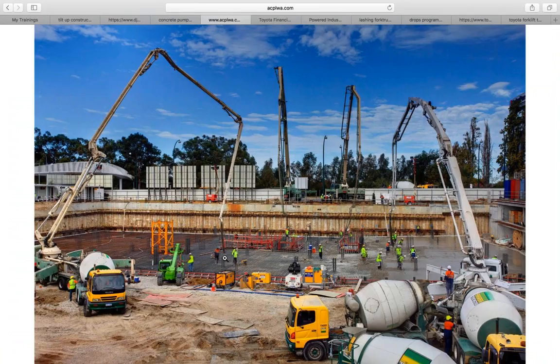Okay. All right, good. And then let's talk about chemical dermatitis and silicosis, right? Obviously, we want to control any type of dust in the air, silica, preferably engineer the hazard out. If we can't, then we go to PPE. Where does it come from? Often Portland cement, mortar, sand, so brick and block, so different cuts of brick and block, so different hazards that we have with silica. Things that we need to do in order to minimize the risk of chemical dermatitis or cement dermatitis, or silicosis, is wear coveralls or protective clothing, long sleeve shirts, boots, rubber gloves, goggles, face masks,